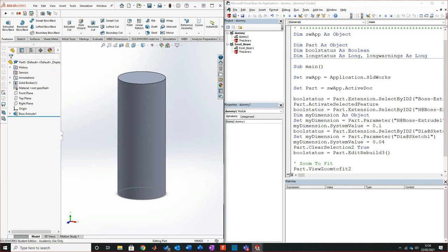And so I don't want you to think that for your assignment it would be more than acceptable to just simply import a rivet. Because you just wouldn't do it. You'd speed it up. It's much quicker to actually code it. So springs, screws, nuts, bolts, they all fall under the remit of needs to be modeled from scratch. Something like suspension, a full suspension, alloy wheels, anything like that, that would be something you would import due to the actual geometry levels and the amount of stuff that you have to do to it to get it working.